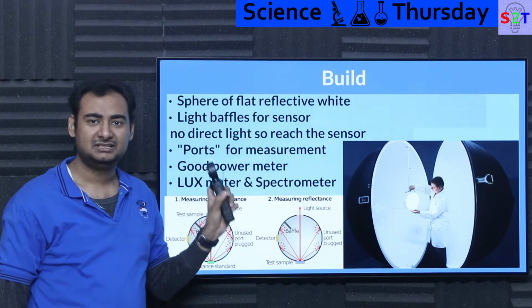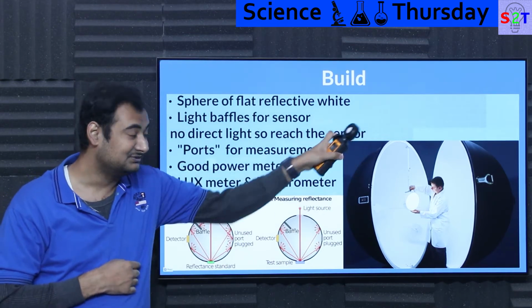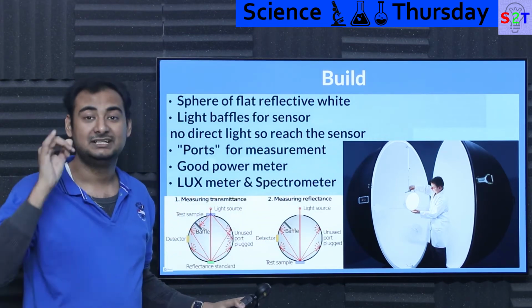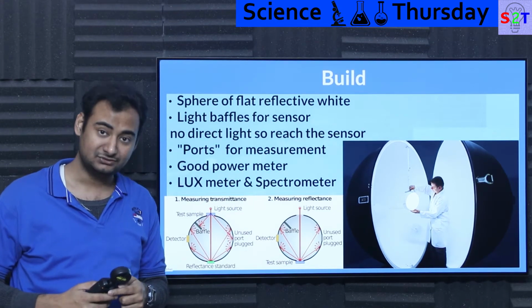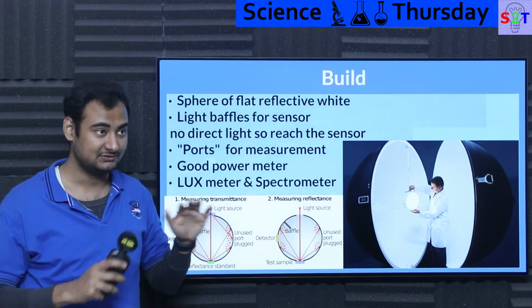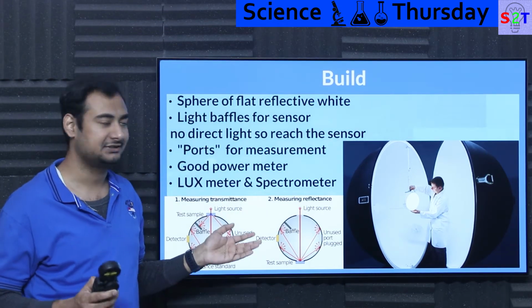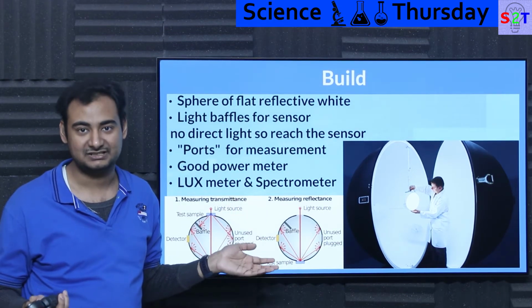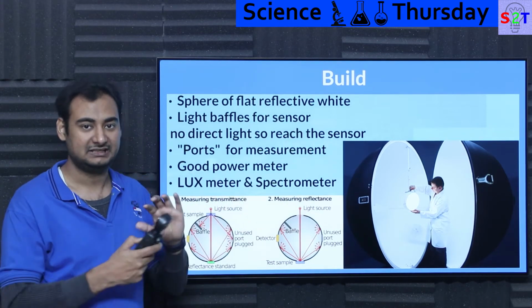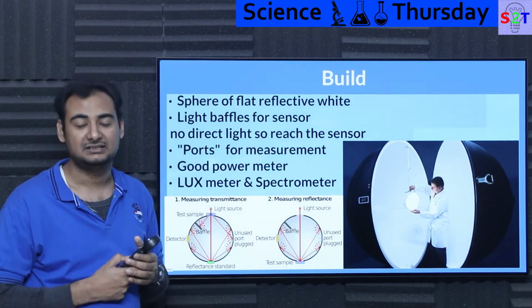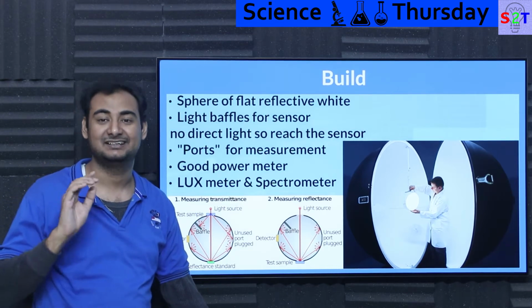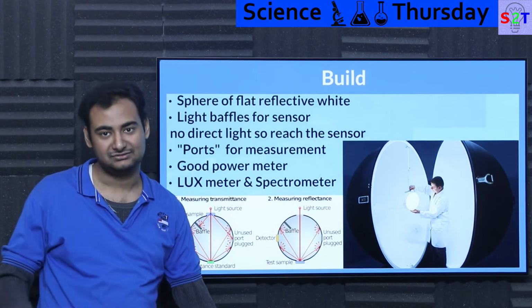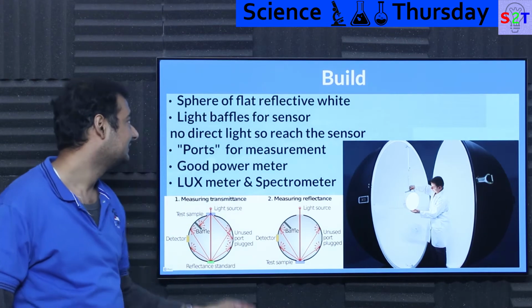Now you're like, wait a minute, I said this is useless, but I specified the diameter of the sphere mixing all the light. That's how you can calculate the lumens. Basically, how big the sphere is, and of course you're going to assume it's 98% or 100% efficient, and then you do your mathematics. If my meter is reading, let's say, 10,000 lux, and the diameter is this much, then you can calculate the lumens output. So that's the whole point.